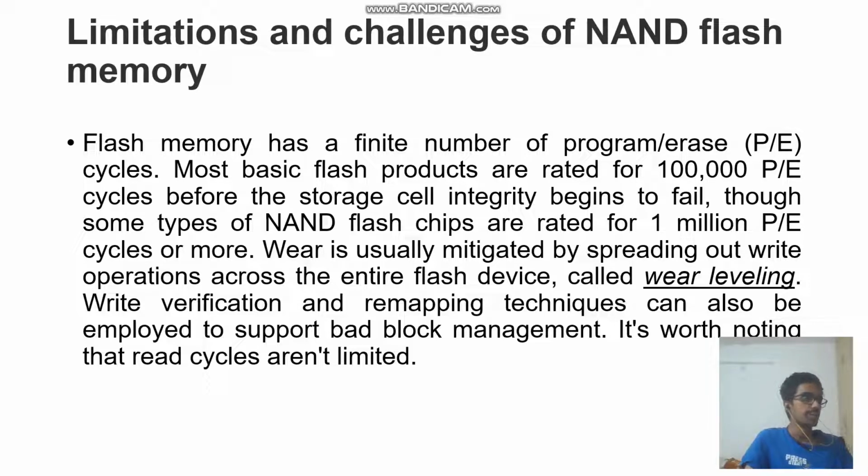Wear is usually mitigated by spreading out write operations across the entire flash device, which is called wear leveling. Write verification and remapping techniques can also be employed to support bad block management. It is worth noting that read cycles aren't limited.